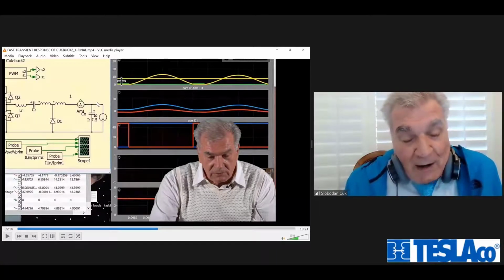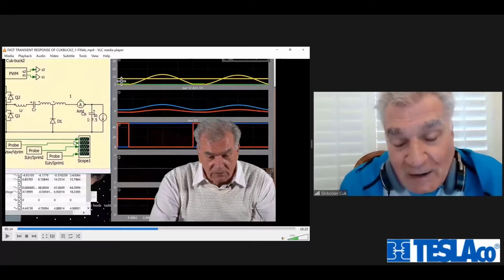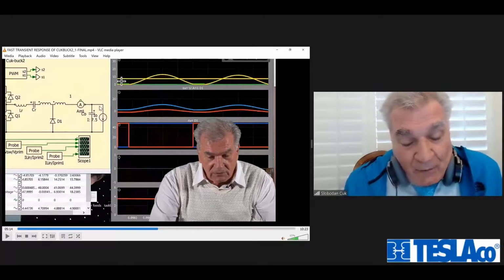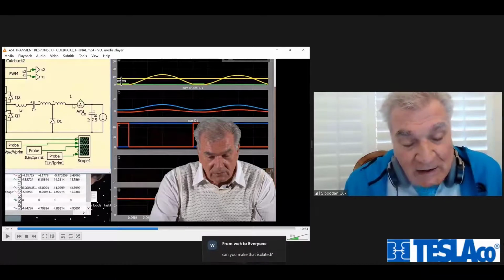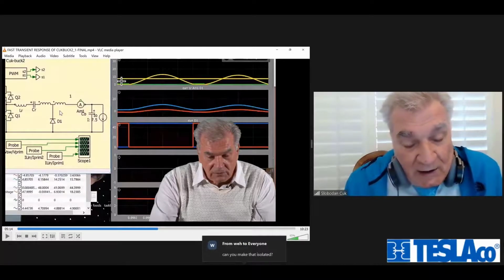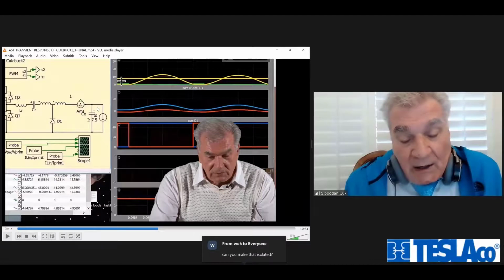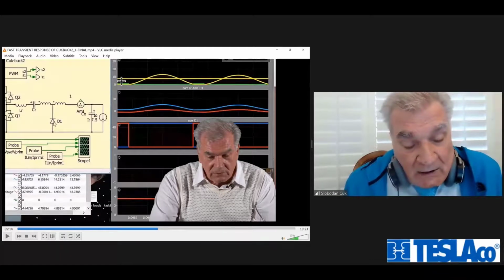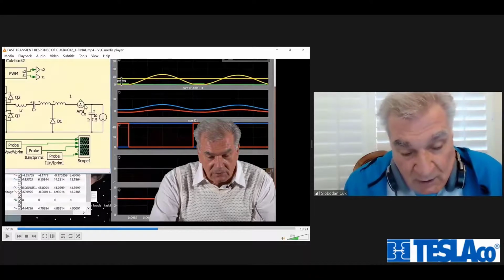Now I have a capacitor on the secondary, which is nothing, and yet it has a constant current, and it changes abruptly. Whatever current on the secondary says, it drives the magnetics in such a way to draw whatever current is needed in the next cycle. It never goes into the negative part. This is zero switching losses and zero ripple on the output, literally.